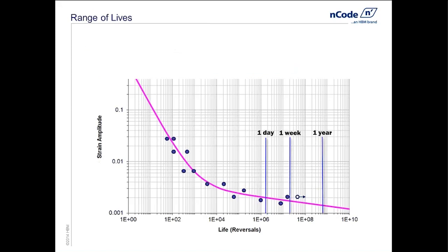Here we're looking at just an arbitrary strain life curve, and we're fitting through data. The blue dots here are all data points. This one point out here, with the circle and the arrow, is a designation of a runout. This is a test that we stopped at about 20 million cycles. That test was terminated, and that data point isn't used in the determination of the strain life curve at all. Now, one thing we want to identify is the valid range of data.